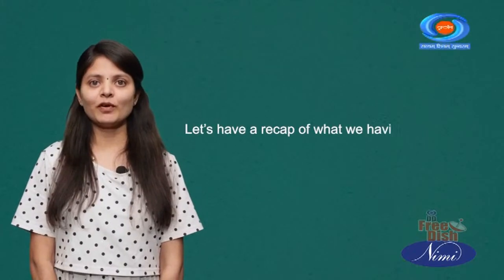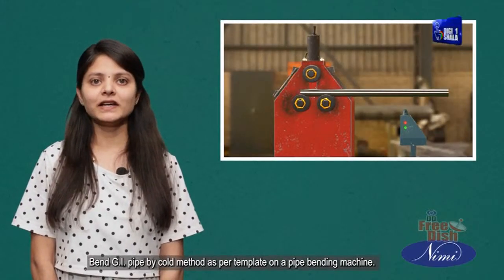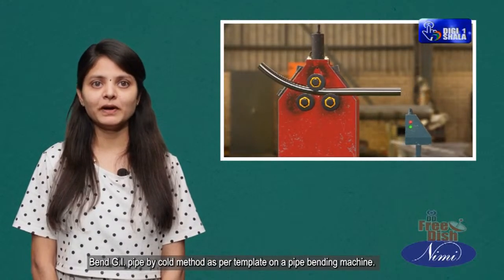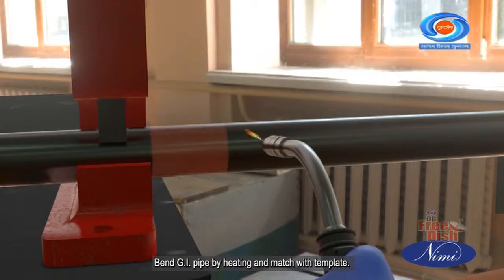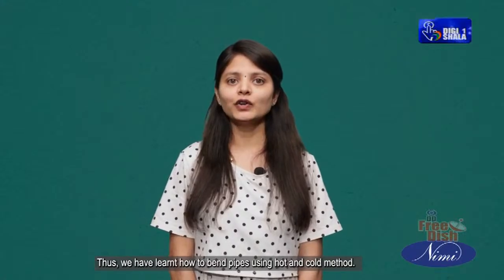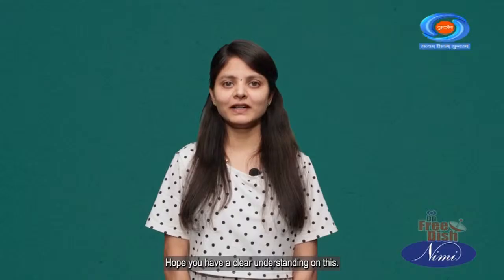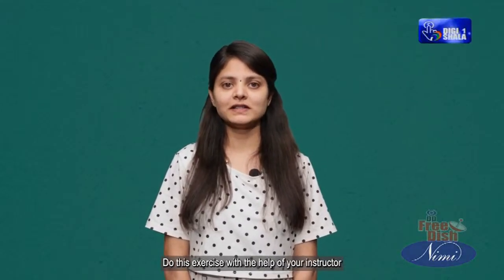Let's have a recap of what we have learned today. We have learned to bend GI pipe by cold method as per template on a pipe bending machine. Bend GI pipe by heating and match with template. Thus, we have learned how to bend pipes using hot and cold methods. Hope you have a clear understanding on this. Do this exercise with the help of your instructor.